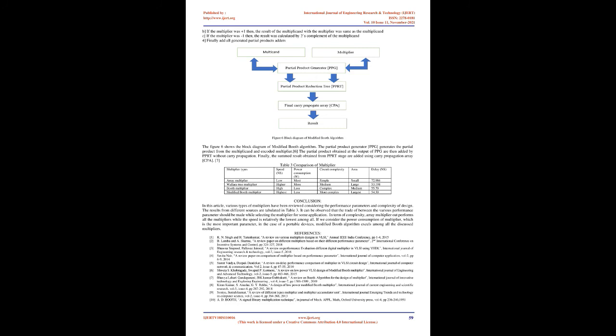Algorithm. 1. Check whether the multiplier and multiplicand have a negative sign. If so, convert to 2's complement. 2. Add an implied 0 to the multiplier and then convert the multiplier into another form using the Booth recoding table shown above. 3. Now multiply the multiplier with the multiplicand.